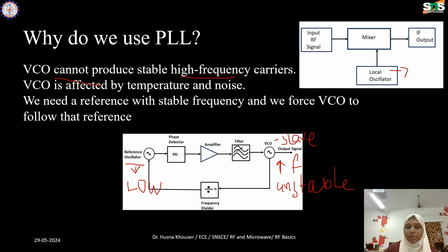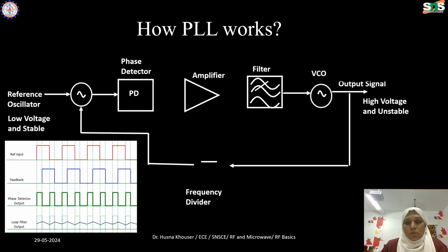So this is the reason why we go for this PLL. The PLL has a proper systematic approach to convert from this unstable VCO to a stable frequency with respect to the reference oscillator. And now we'll see how the PLL works.